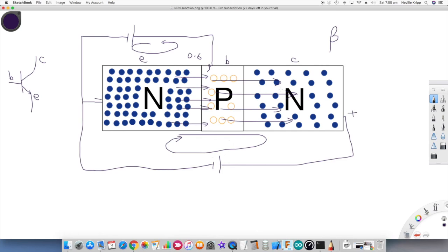So one other thing that we should mention is if we turn this emitter base junction on quite hard so that the transistor is fully on, then the current flow through emitter collector will saturate as well, and effectively we've generated a switch. So this is the transistor being used as a switch. We either turn it off fully or we turn it on quite hard so that the device saturates, and that's the basis of using the transistor in a digital circuit. Two states, on or off.